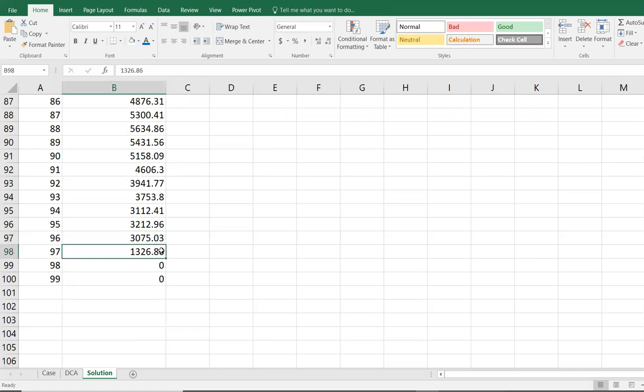It seems unnatural. Maybe there is an abrupt, severe formation damage, or maybe there is an operational problem, a well problem, maybe an artificial lift problem, maybe an operator chokes back the well. We don't know. But the data shows there was a significant decrease of production, which seems unnatural.